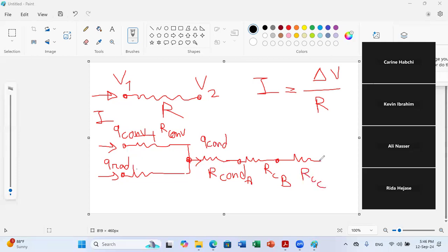At the end of your envelope, you have the inner temperature, T inner. So here we have T inner. Here, at this node, you have T outer. And here you have, let's say for convection, convection with T infinity 1. While for radiation, for example, let's say you consider radiation with the sky. So I can give you the temperature of the sky, T sky.